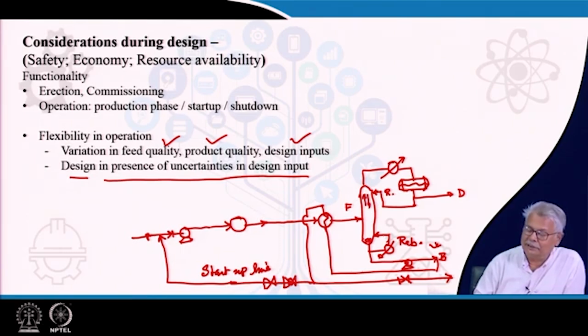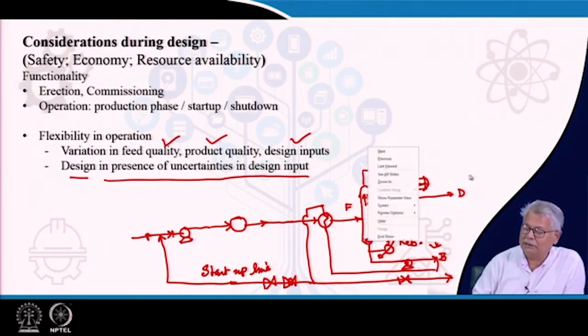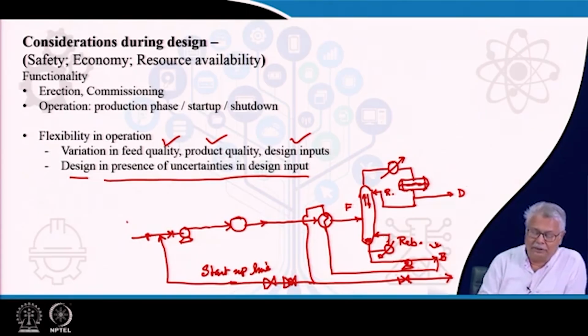After some time the entire column will get heated and liquid will start coming into your reflux drum, and your reflux drum will be having a level. Quite naturally, since some of the liquid which had come here while it is circulating, part of it gets transferred to the reflux drum, you have to take fresh amount of feed.